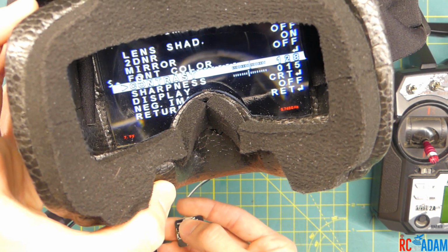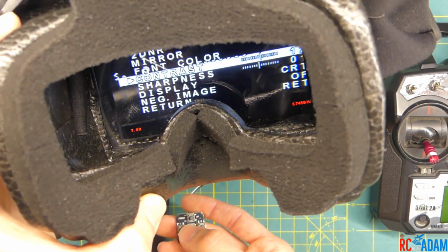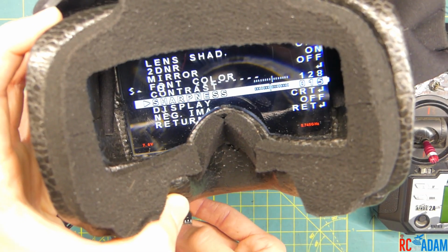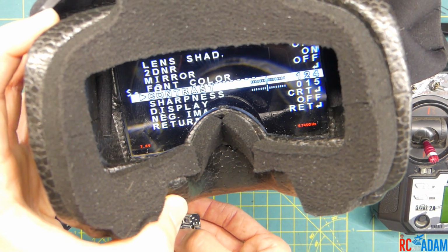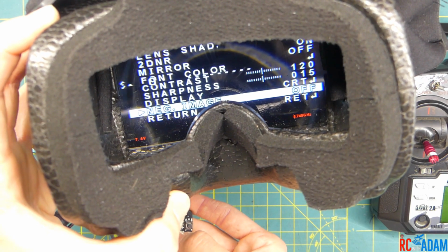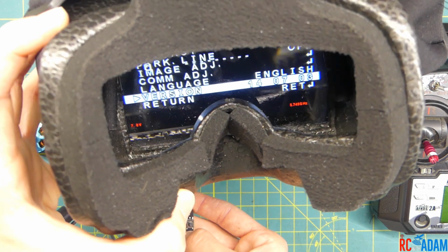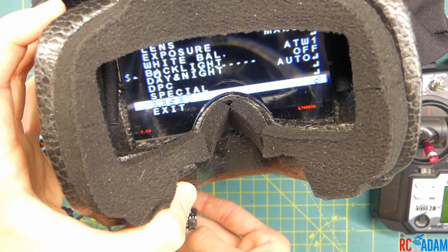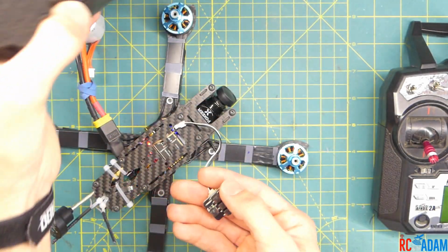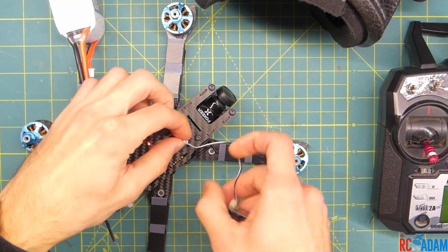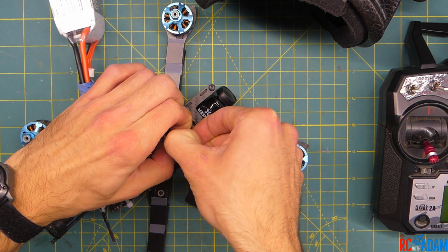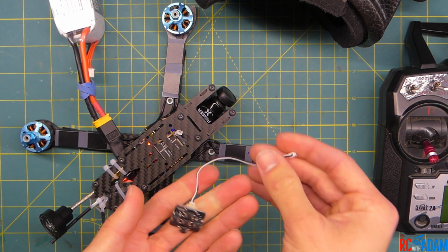And honestly, you want to be looking through this at your flight area, but I'm showing you as an example here. And the contrast, you might want to turn it down or up depending on how you like it. I'm going to turn both of those down just a little bit, and then I'm going to hit return and exit. There we go. So that's how you can change your settings. I think that DWDR is the biggest difference. That's going to really give you that wide dynamic range, and why it's not on there already, I don't know.